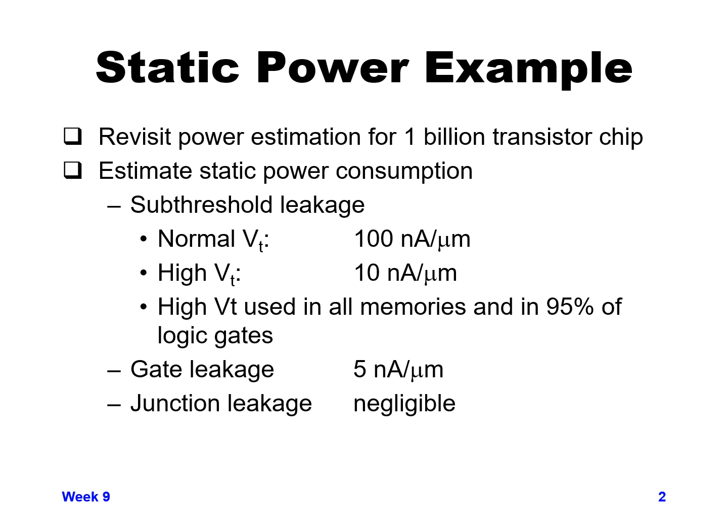Then we have a high VT device, so the higher VT will mean that it's a little bit slower than the normal VT, but its leakage is a factor of 10 less. So we're going to use the high VT device on paths that are not our most critical paths, and it will help us save leakage power, even though those paths will get a little bit slower, but since they're not the most critical paths, we don't need them to be the fastest transistors out there.